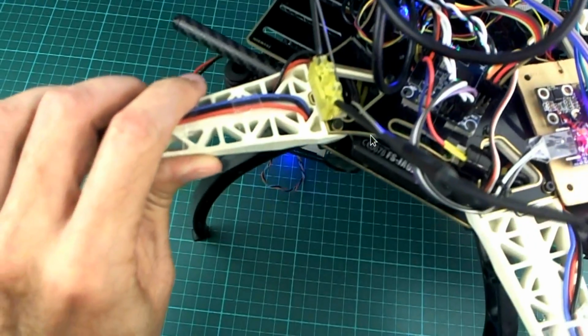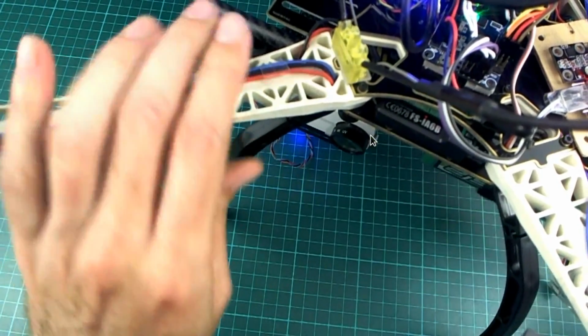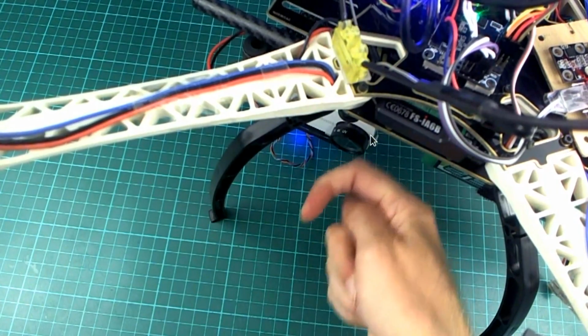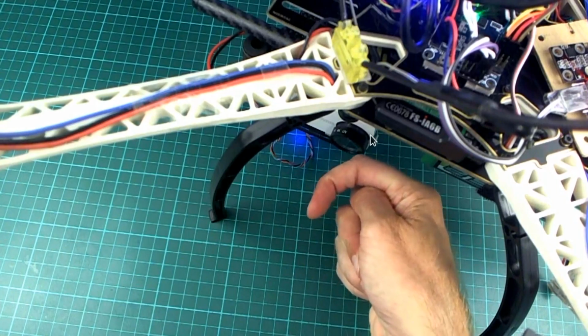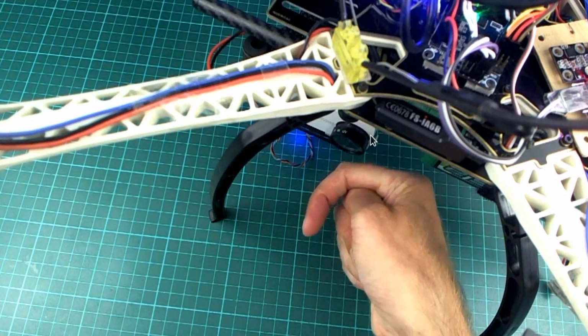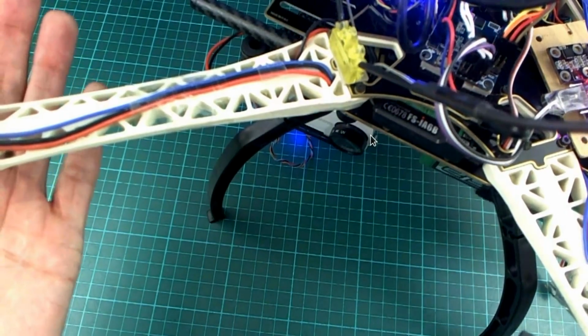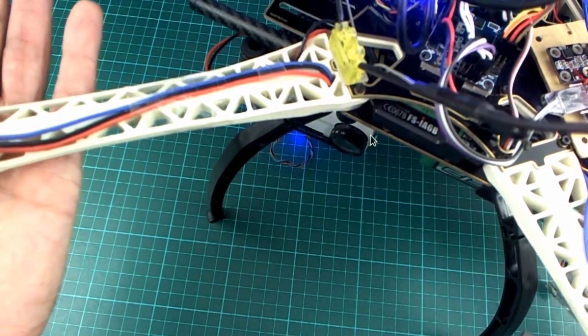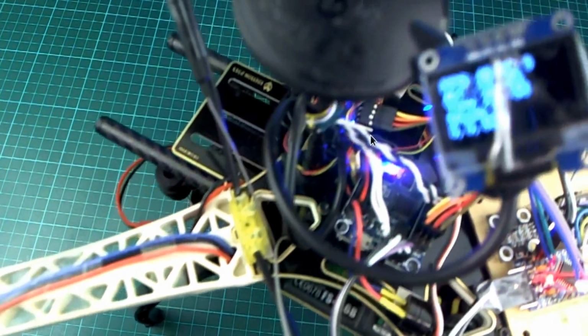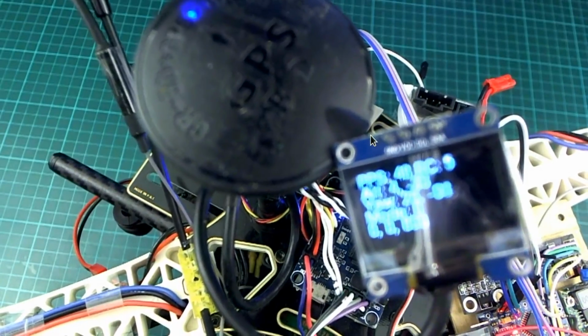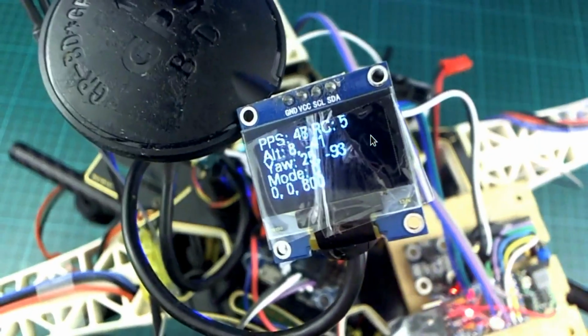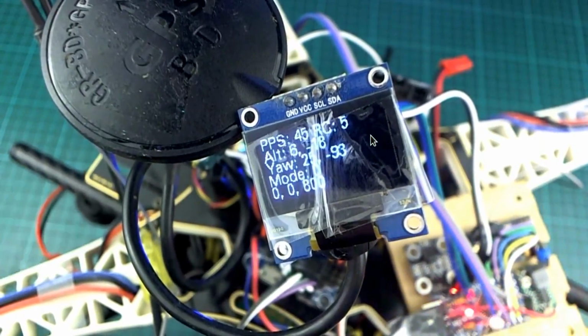So I'm not sure if we can see it there at the moment, but alright, it's facing almost 90 degrees towards the left of the quadcopter, and I can see right now it says minus 93. I'll see if I can bring it back over here without it changing. Okay, minus 93, good. So that's what that means. Minus 90 degrees means 90 degrees to the left.